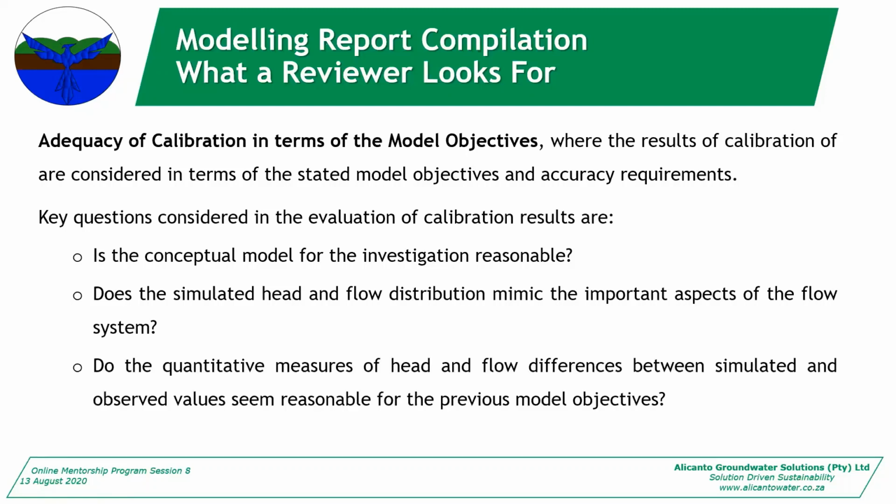Do the quantitative measures of head and flow differences between simulated and observed values seem reasonable compared to your model objectives? So that comes back to your root mean square error and your calibration statistics. Is it reasonable compared to your model objectives, your confidence required?